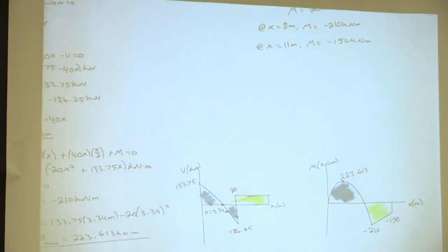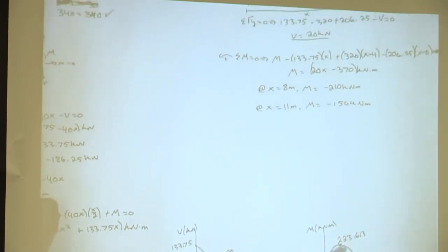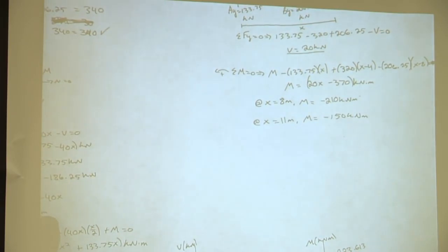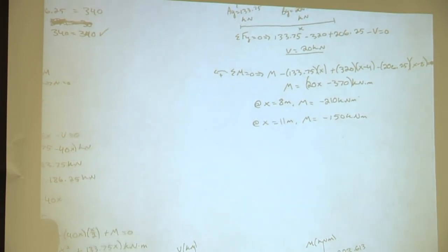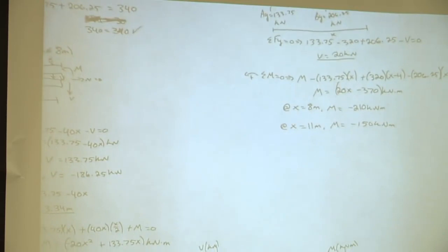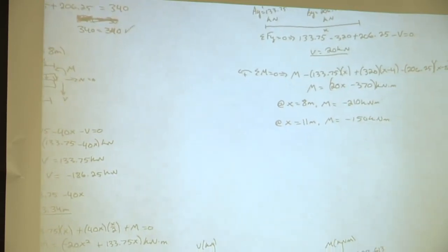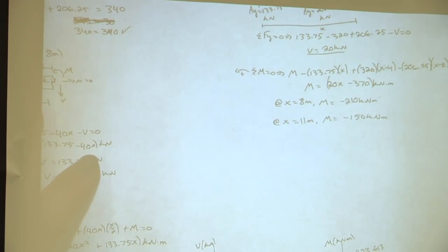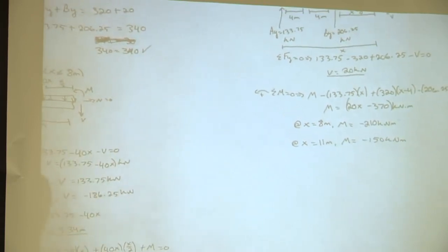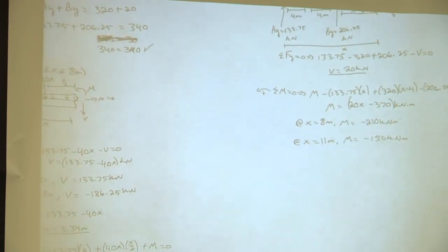So how do we know to do the shear at 0 with the first equation? What if there's multiple shear equations that we could solve for if shear was 0? Say we did another cut, and the shear equation was just another linear equation, Vx equals something. We technically put the shear equal to 0 and solve for it, and would it still come out to be the maximum? Yes. Wherever shear is 0, max bending is always going to be at that location.